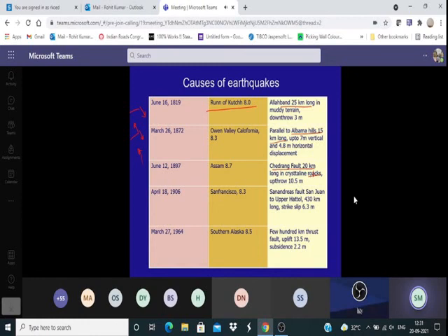Then the California earthquake, the San Francisco earthquake. This is a very important earthquake because the earthquake theory was based upon this. This was on the San Andreas fault, and for 430 kilometers length, 6.3 meters was the slip along the fault. So it means that along around 430 kilometers, between this side and this side, the difference between the displacements was 6.3 meters.